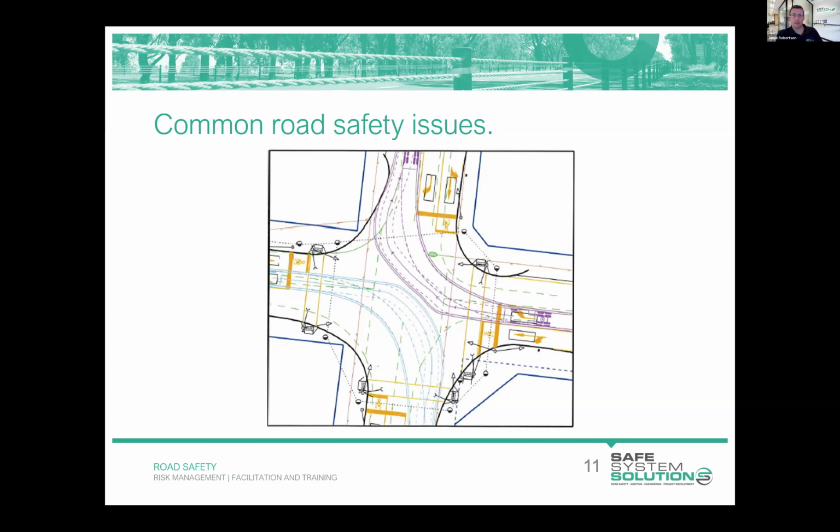There is overhang at the front and the rear of the vehicle, and that's why the vehicle body requires more space. It can be important to know where the wheels are tracking at locations like bus stops or other locations where we might allow overhanging of the curb. So there are options to turn on and off different levels or lines in the AutoTurn software that's used to generate these swept paths.